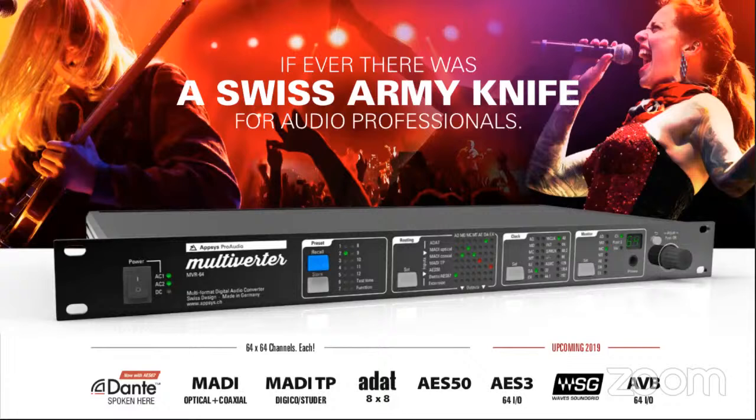There's also external add-ons like AVB and AES/EBU that you can plug into the back and also add AVB and AES3 connectivity. Now, one thing that a lot of people don't realize with this solution is that not only can I do one-to-one stream conversion, like all 64 channels of MADI to 64 channels of ADAT, but I also can do individual channel conversion. So if I wanted to convert Dante channel 16 to AES3 channel 3, I can do that. And that's done through the web GUI.